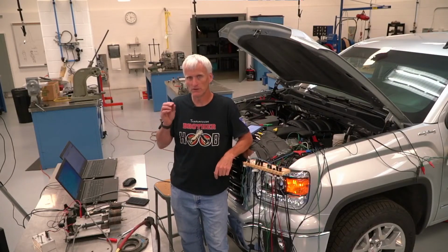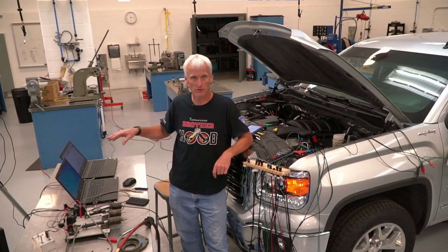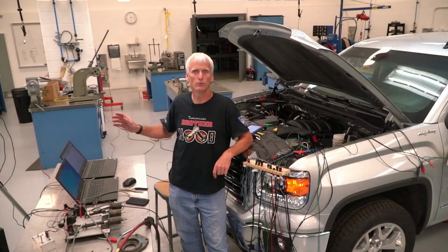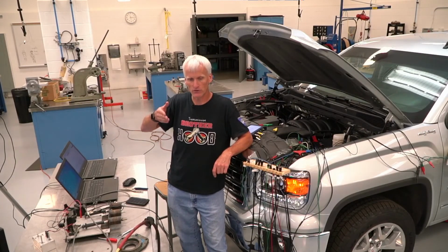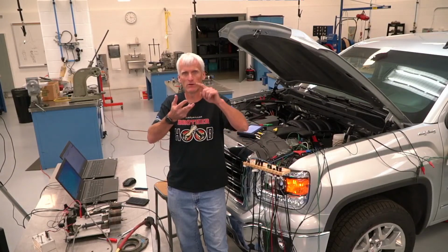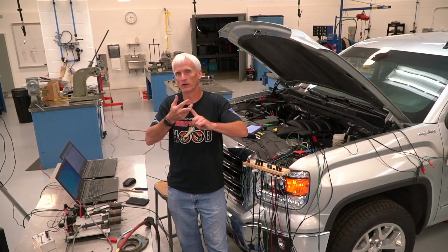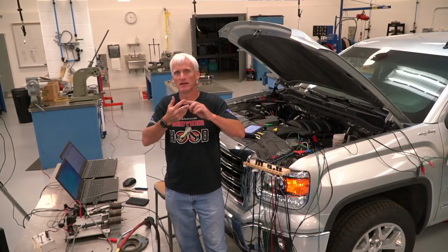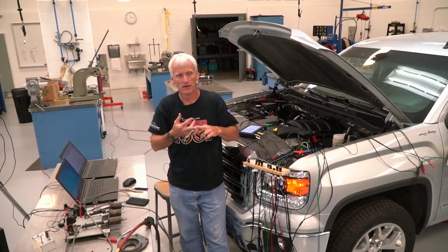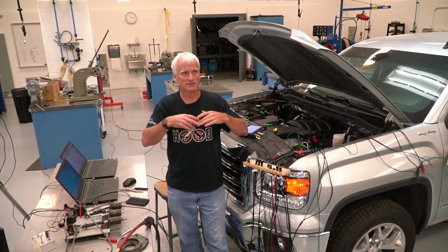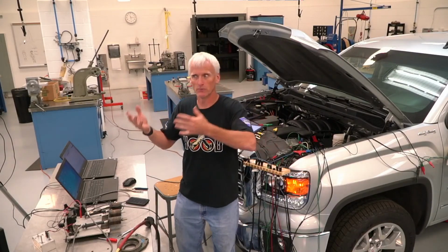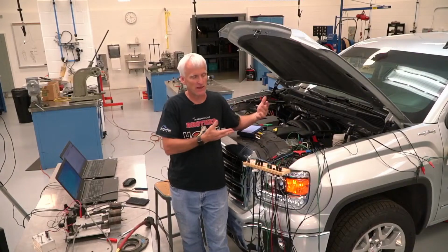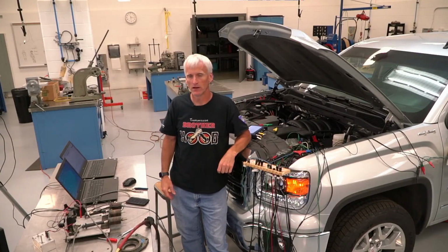And what you have to do is, instead of putting barometric pressure at the real barometric pressure, you put the maximum boost pressure that you got where you're taking your readings, the RPM, the mass airflow. Look to see what your absolute manifold pressure is, and enter that into the calculator. And basically you're treating it as if the barometric pressure is what your boost is. That way you can see if that would actually equate to a proper airflow.